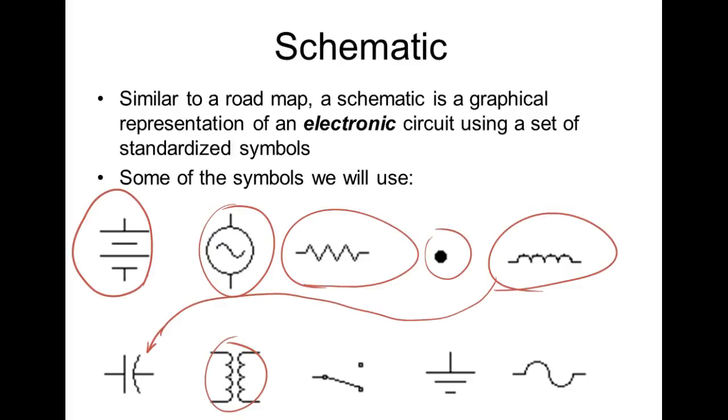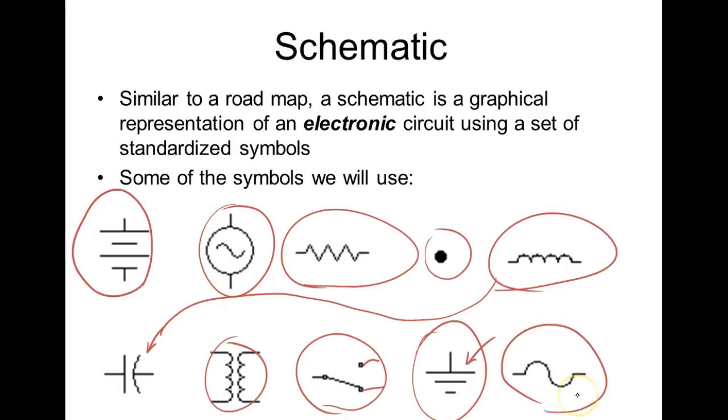No, they don't step up or step down power. Voltage, yeah, they change. If it was an ideal transformer, it wouldn't change the power at all, but it does just a little. This is a symbol for, well, usually when we see the two dots, it would be a single pole double throw. But usually they put the lines up there. This is a symbol for a ground. We have a different symbol for common. This is usually misused though. This is a pretty standard symbol. So you're right, but it's not technically right. And this is a symbol for what? A fuse. That's a symbol for a fuse.